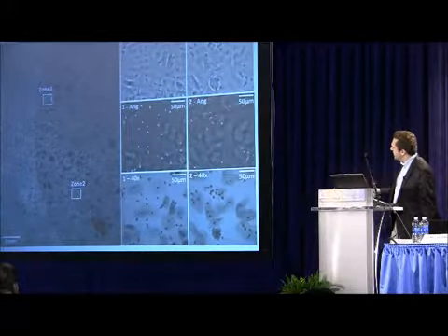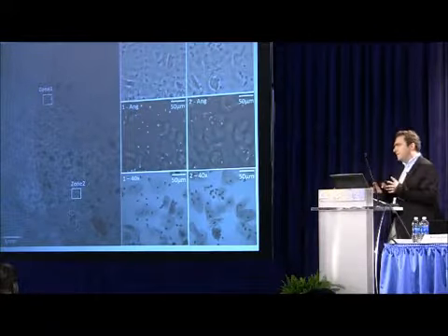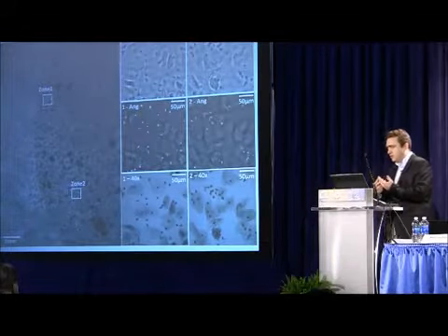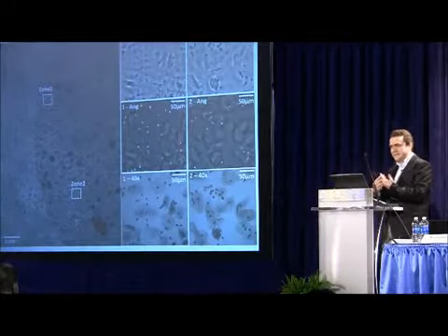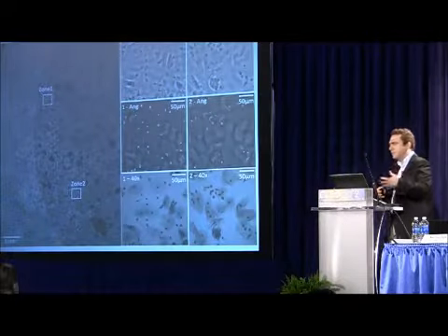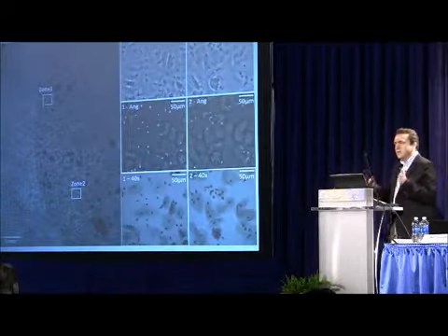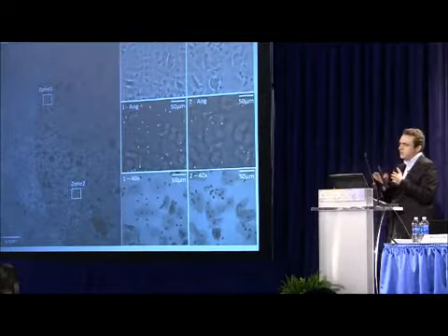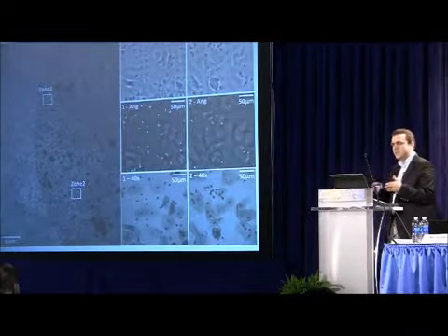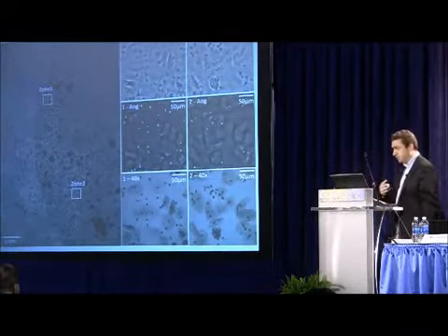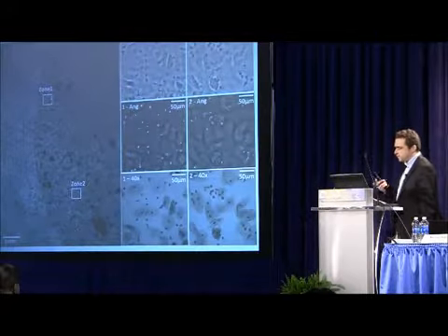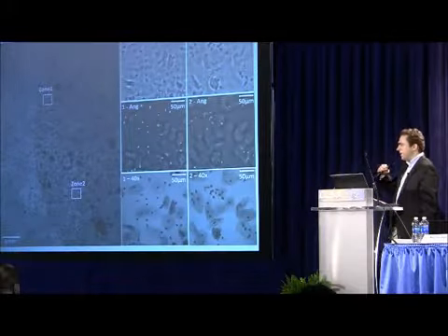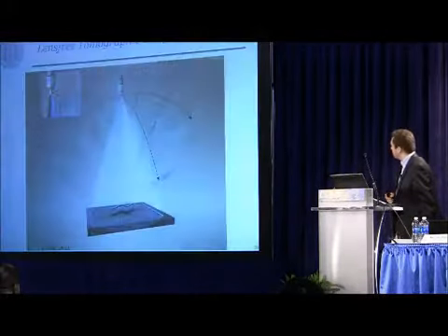And in this case, the field of view is around 30 millimeters square. So the field of view scales with the sensor. That's kind of a unique feature of lens-free computational imaging. It can follow Moore's law qualitatively, in the sense that next generation sensors, which would be 15 megapixel, 20 megapixel, would not trade off anything in our design. And it's going to enlarge the field of view without degrading the resolution. And sometimes it's going to improve the field of view and resolution at the same time, depending on the design of the CMOS imager. And that's where you can really follow, with your microscope, without changing your construction, a trend which improves the field of view and resolution at the same time.